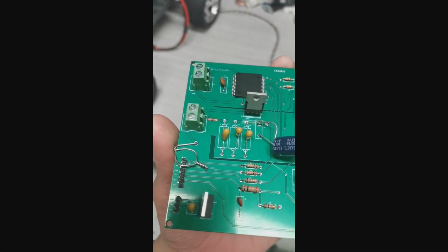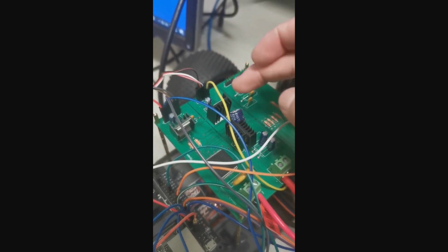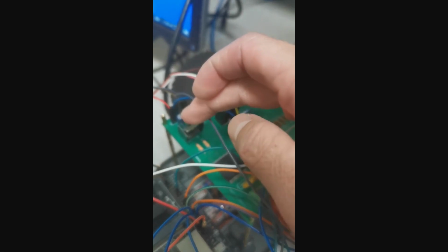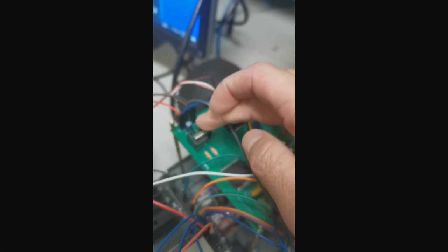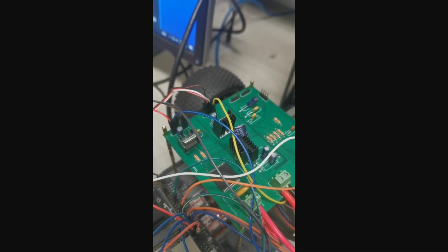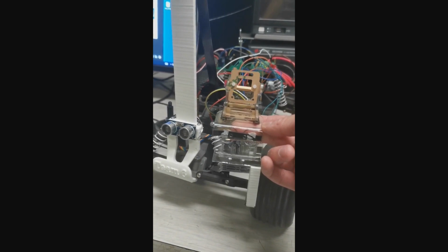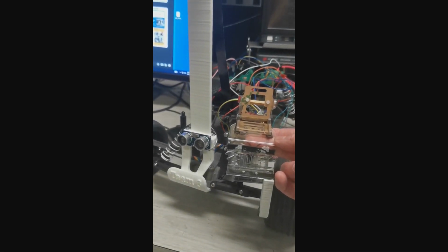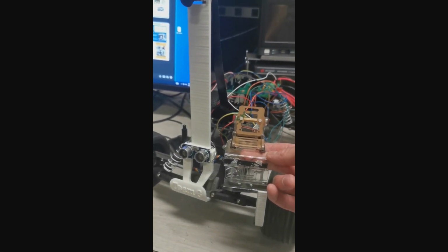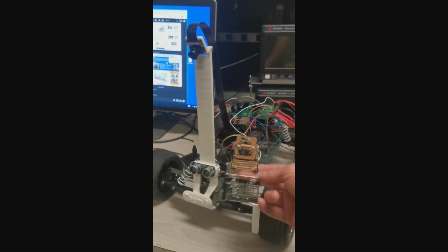As we proceeded with the test rounds, we discovered that the camera angle played a critical role in lane detection. It became evident that detecting the lane at a farther distance compromised the car's stability during turns. To rectify this, we designed a 3D printed camera support rod extending the height of the camera. This adjustment allows us to detect the lane precisely beneath the front wheels, enhancing the car's overall performance.